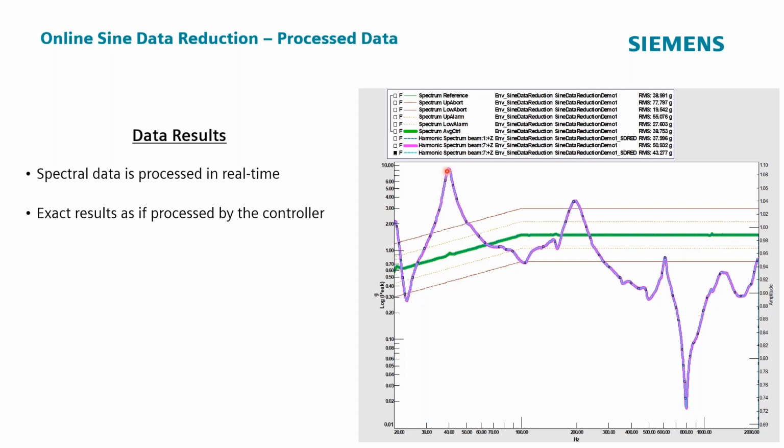You can get pretty close by using a peak hold method of averaging, but still post-processing time data in a standard analyzer is just going to give you basically FFT analysis, which is not really what a sine controller is doing. It's not taking a block of data and doing an FFT to get a frequency and an amplitude. It's applying one of those estimator methods that we discussed.